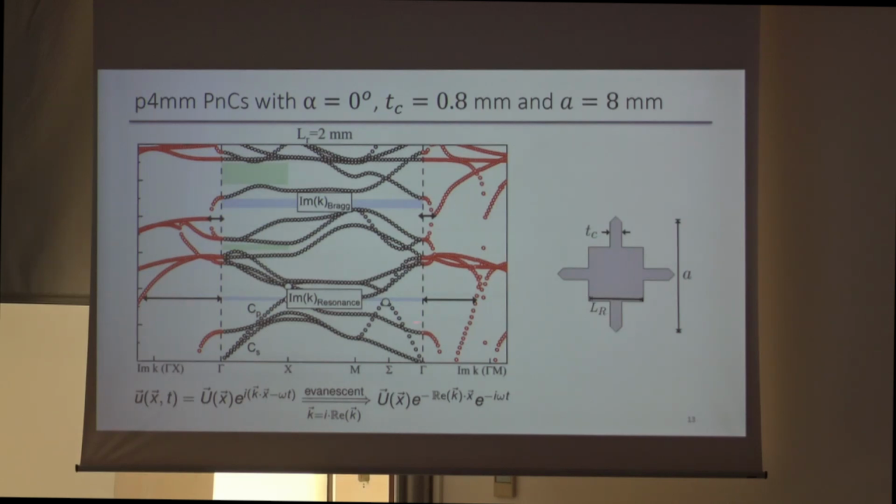So just by measuring this k, we can say whether the band gap attenuates better or not. This lower one is the resonance band gap, and the top one, where k is very large, and they also meet here in the middle. You have kind of a hat here. This is the marker of the Bragg band gap. So this is how we can understand how good our band gap is, meaning its attenuation performance, and also its type: whether it is a Bragg or a resonance band gap.